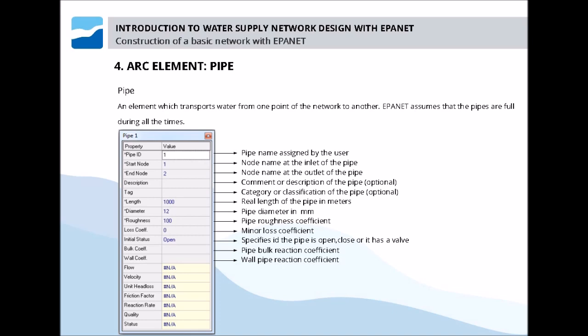Before moving on, I would like to mention very briefly the different calculation methods we can use. First of all, there is the Hazen-Williams method. It is mostly used in the Anglo-Saxon world. It cannot be used with any other fluid than water, and it was originally developed for a turbulent regime.